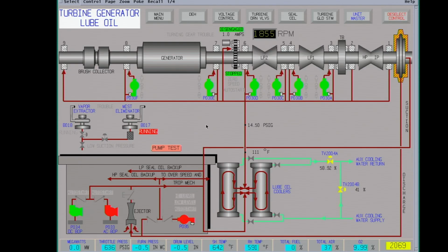Okay, our lift pumps have shut off. Oil temperature is about 111, 14 psi. These pumps here will be swapped over at 3600. There is a pump on the end of the turbine shaft that produces high pressure oil, about 350 psi. That oil comes down to an ejector. The high pressure oil is used to move a large volume of low pressure oil, which feeds the bearings. And some of the high pressure oil goes for feeding the hydrogen seal. There's also an overspeed setup.